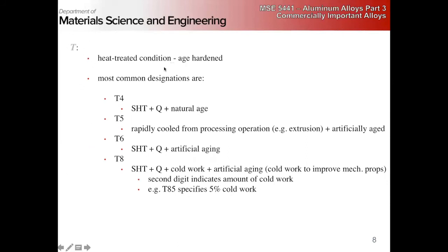T is the heat treatment condition, right? These are for age-hardened alloys only, right? The most common designations are T4, which is solution heat treated and quenched and then given a natural age, right? So the natural age here means room temperature.